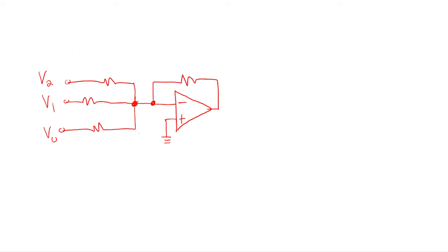If you wanted to, you could do nodal analysis without doing superposition pretty easily, and just say this current, this current, this current equals that current. Is there anything wrong with doing that? Because that's what I did to answer this last night. Nothing wrong with that at all. What would the current leaving the node that connects all three be equal to, if there's no element?